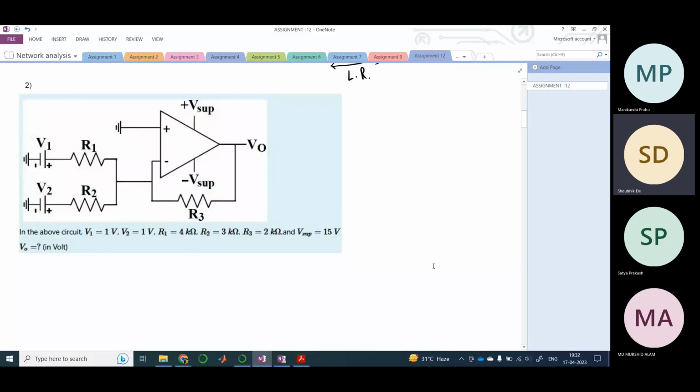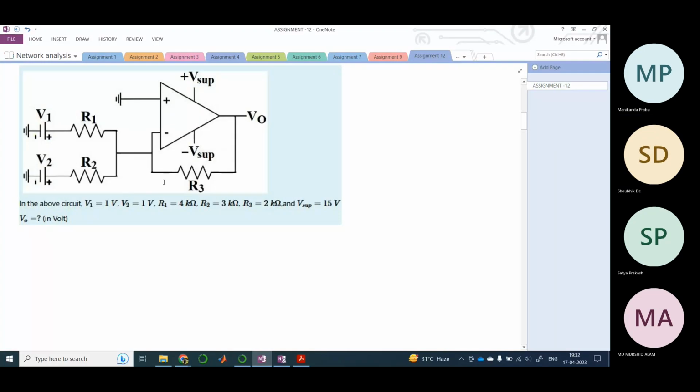Okay, so now this is a negative adder circuit. We will see how. See, this part, the non-inverting terminal, is grounded, right? Therefore, if this is grounded, this part also becomes grounded. So if this is zero, this part also becomes zero. We will represent it as node X here, and when this condition is satisfied, you can take this whole op amp out of the picture.